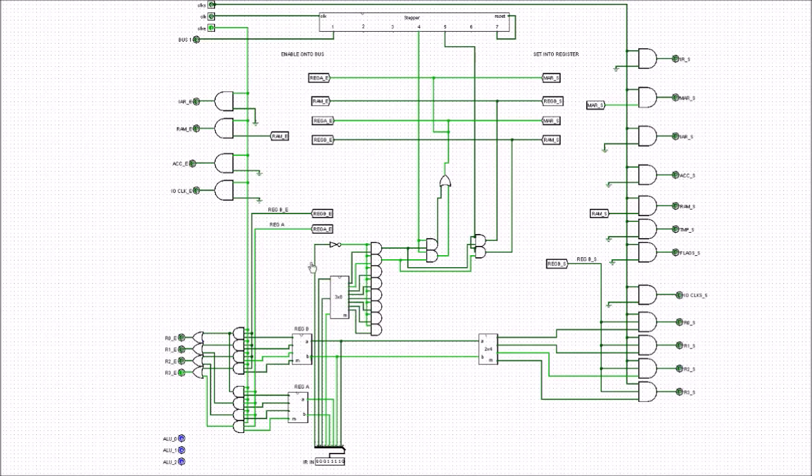Now, if we were to, say for example, look at the most significant bit here, if that most significant bit happened to be a 1, then we know it would be an ALU instruction. So if that was a 1, it would mean that this side here would be a 0, and these zeros would all go down to the AND gates. That would mean that these AND gates in effect wouldn't function, so the output for these AND gates wouldn't be determined by the values of the inputs here.